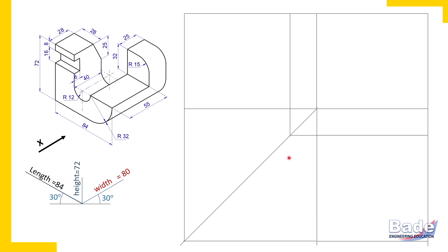Now we'll proceed. So here we'll focus on principal surfaces and principal edges. What exactly is a principal edge and what are principal surfaces? To know that, watch video number 2 on orthographic projections. Let's proceed. Now watch this surface. This surface has 2 principal edges which are perpendicular to each other. This edge, remember again, edges which are perpendicular to the reference axis are principal edges.